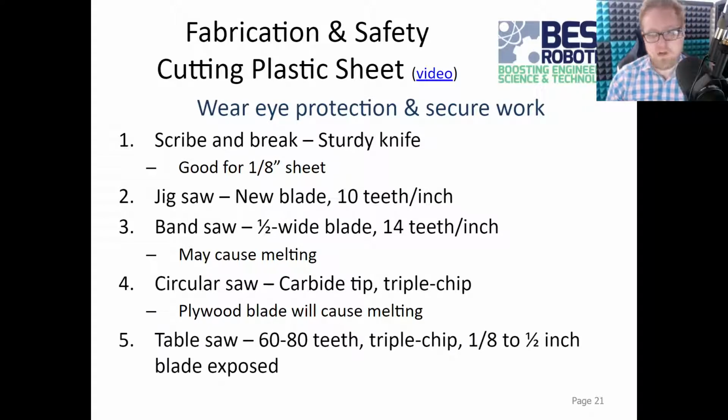So starting off, we're going to talk about some of the plastic sheeting. For the thinner sheeting, while all of this can be cut with saws, if you have sheeting about 1/8 of an inch, the best recommendation is that you don't always have to cut through it to get a nice line. You can use a scribe. There's some glass cutting knives you can get from Home Depot that will work, or just a standard utility knife that allows you to score part of the sheet.